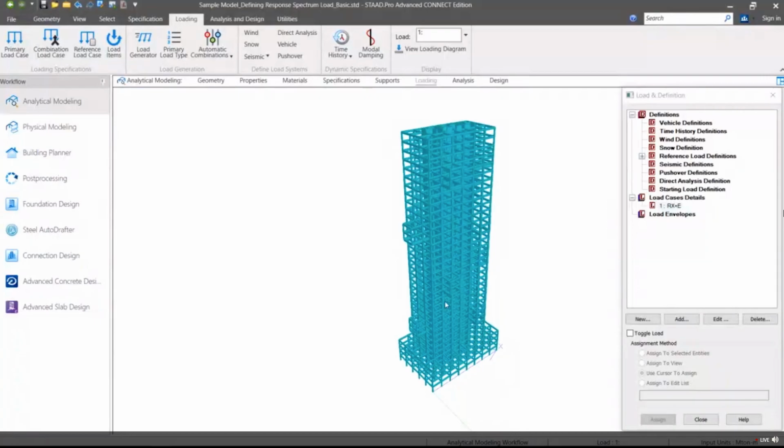Or, similar to mode number selection, you can check this with the same model before defining any load case. I am using a copy of this model. First two load cases are static seismic load in X and Z direction with load factor 1 and without considering any torsion input, as that is not relevant for base shear calculation. Similarly, two spectrum load cases are added in X and Z direction with direction factor 0.28 as discussed earlier.